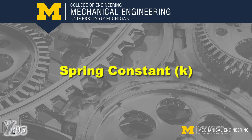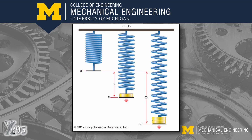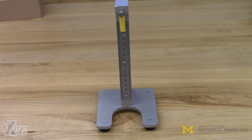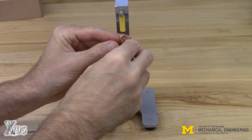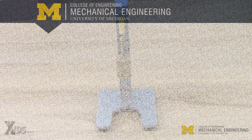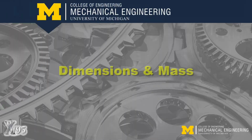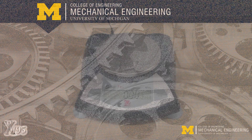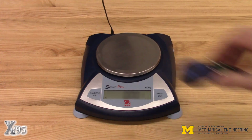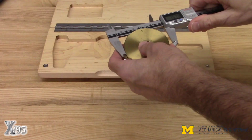The spring constant, denoted K, can be experimentally determined by measuring the rate of deflection to a varying load. Use the provided fixture to incrementally hang weights from the spring and measure the ensuing deflection. Fit a line to the plotted data to calculate the spring constant. A surrogate flywheel and lever arm are provided to measure the mass and applicable dimensions.